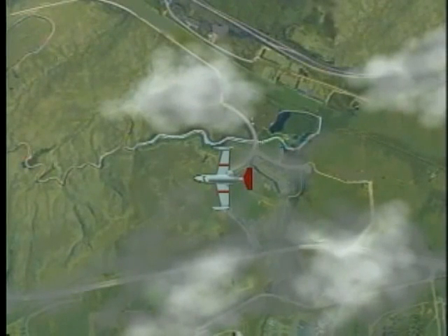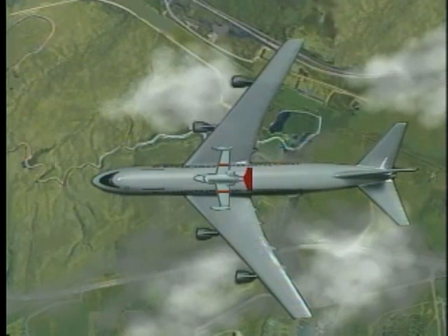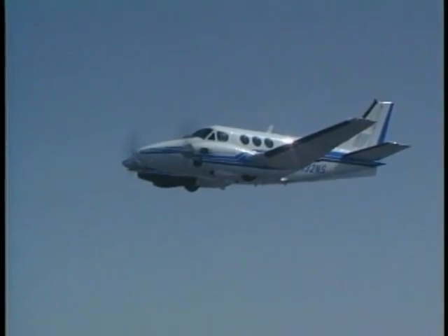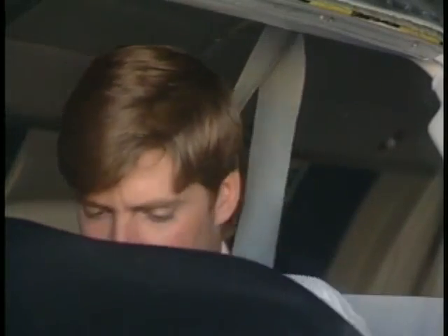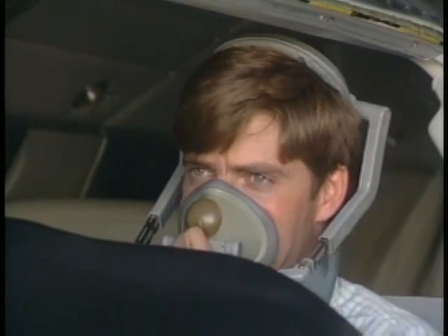Typically, a small aircraft can be expected to decompress 10 to 200 times faster than a large aircraft. A Learjet with a cabin volume of 265 cubic feet will decompress 223 times as fast as a Boeing 747 with a cabin volume of 59,000 cubic feet. An explosive decompression, which occurs in less than half a second, is dangerous and can cause lung damage. If a decompression occurs, pilots should understand what corrective action to take. Supplemental oxygen should be used and a rapid descent should be initiated. These actions should be taken immediately to avoid the onset of hypoxia.